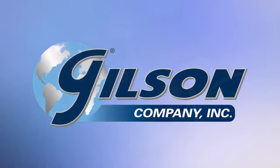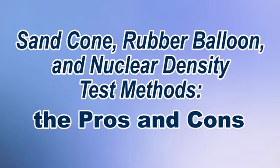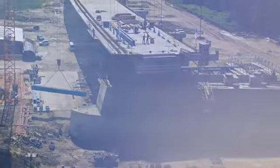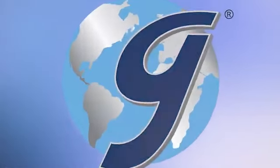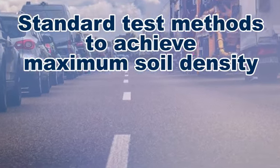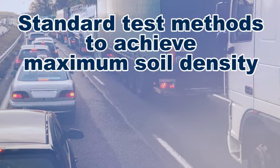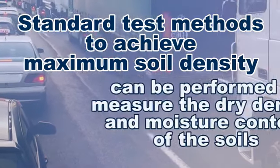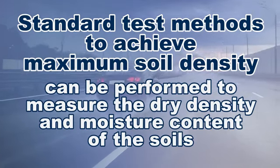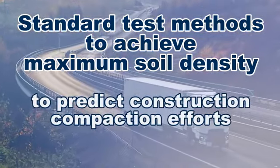Soil compaction, common to construction projects, increases the strength and stability of soils to support earthworks, structures, and pavements. Standard test methods to achieve maximum soil density for the anticipated loads, whether those loads will be static or dynamic, can be performed to measure the dry density and moisture content of the soils and thereby predict the adequacy of construction compaction efforts.